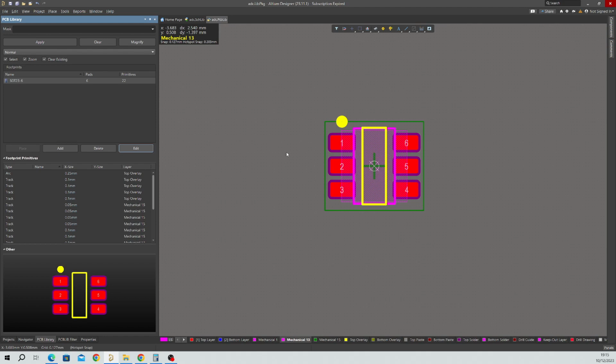Whereas if you assign a generic part to a load of different ADCs or references or op amps, all use the same sort of SOT 23 package, if you modify that one footprint, you're going to affect all the parts. So you need to be careful what you do versus a generic approach, or a little bit more effort but more flexibility, but a unique part number to unique footprint association.